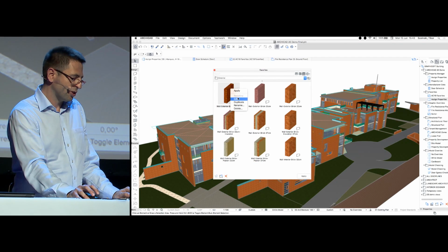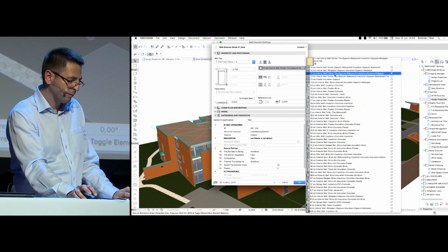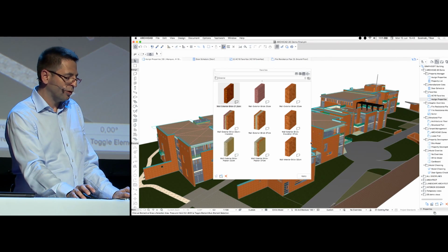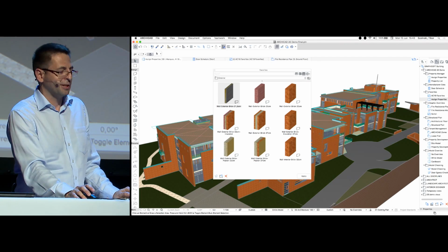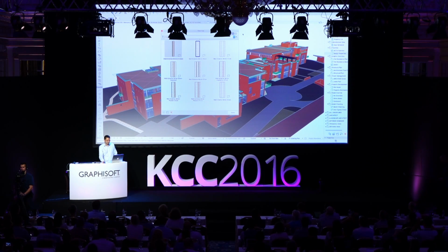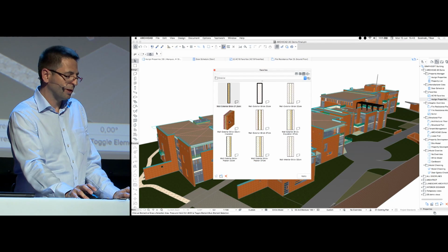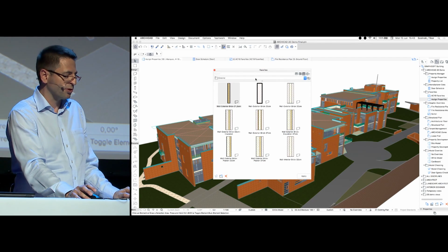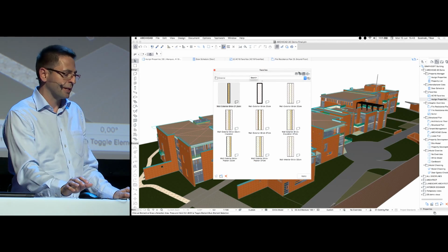All you need to do is just edit one of these favorites. For example, I will choose a different composite structure. And using OpenGL, ARCHICAD automatically updates the previews. That is, again, a real productivity improvement. In certain design scenarios, 2D previews would be more useful. And we can also switch that with a single mouse click. Furthermore, using a control click, you can switch between 3D and 2D views. So I think it's really a convenient way to understand what these favorites are actually used for.